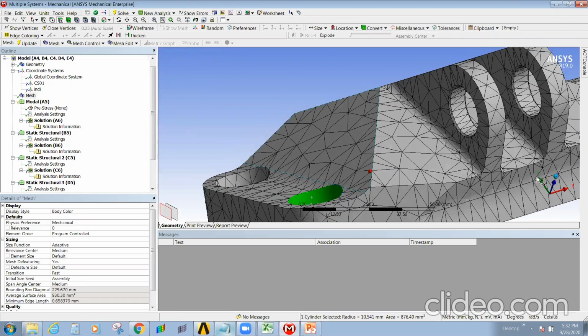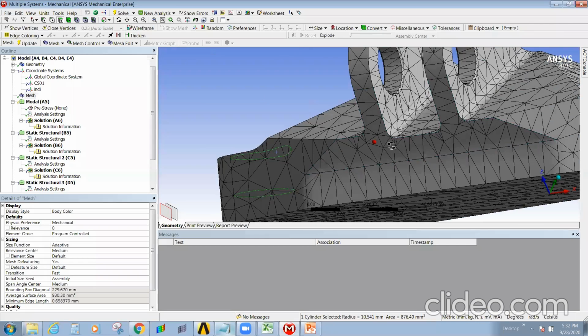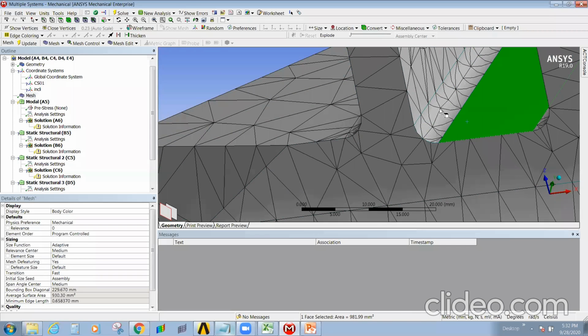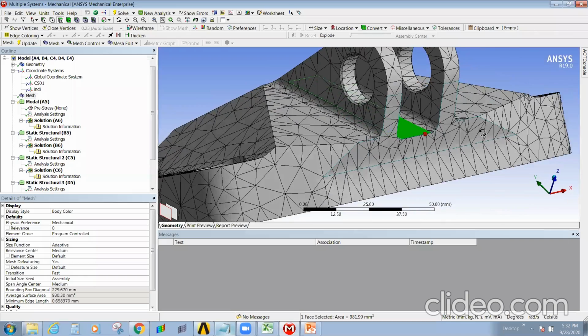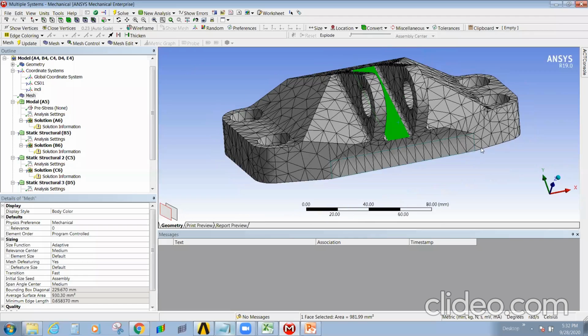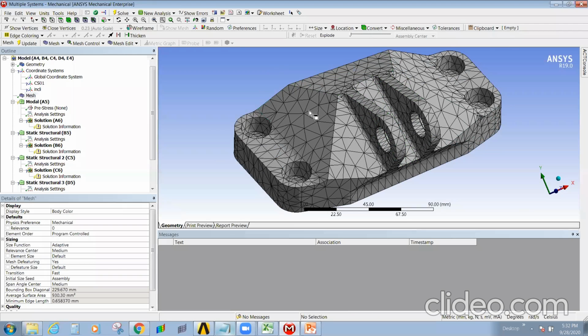Because the fillets are more critical in our design, we need to concentrate on the fillets, whether they fail or what changes we need to make. So a minimum of two elements will be selected at that region. Your software will automatically update the fillets with two elements. This is the speciality of Ansys. It automatically reads your geometry and gives the requirement-based mesh. So your mesh is updated.